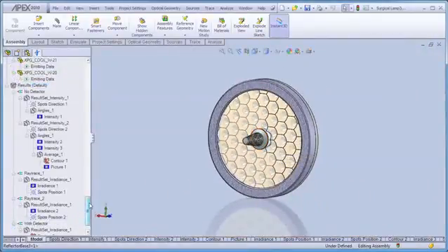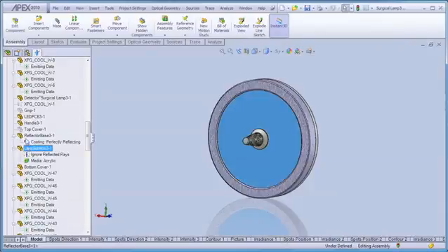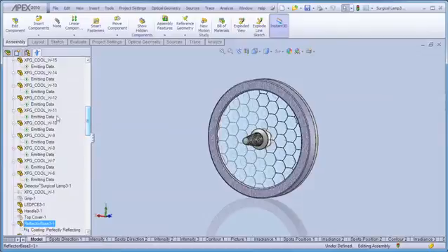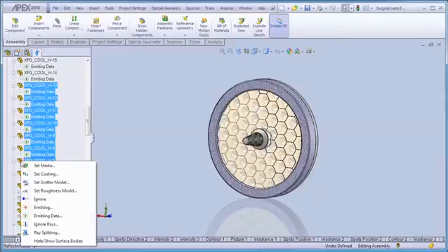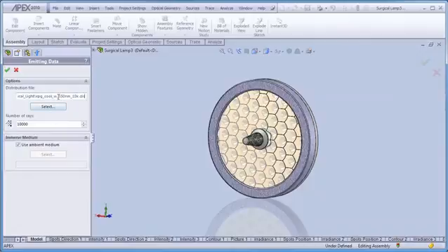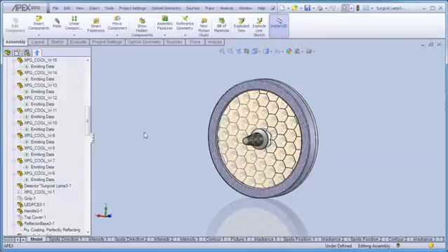Under the APEX Optics Manager, we can quickly assign media and coating properties to the lens and to the reflector, and these are the main optical components of concern to us. In addition to our ability to rapidly create patterns of sources in APEX, we can also select groups of source geometry with the Optics Manager and easily assign a manufacturer's ray data file to all sources simultaneously. Again, this makes the process of creating multiple sources within APEX fast and intuitive.